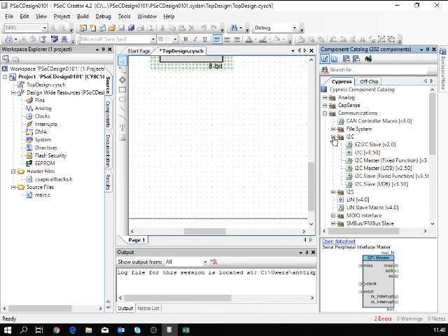So you can use this as an I2C device where an external microcontroller can read or write certain memory locations. It works, and it's probably the easiest way to connect to a Raspberry Pi, since there you have the I2C, and you can even write higher level language code with Python to access the I2C bus.